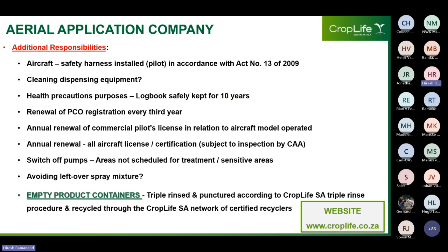Finally, before we move on from here, let me quickly touch on some other responsibilities worth noting. The aircraft must have a safety harness installed for use by the pilot in accordance with the Civil Aviation Regulations of 2011 of the Civil Aviation Act, Act number 13 of 2009. When it comes to cleaning equipment, it is the pilot's duty to ensure that dispensing equipment is thoroughly cleaned and rinsed directly after completion of the spraying operation to prevent contamination of the new batch of spray mixture.